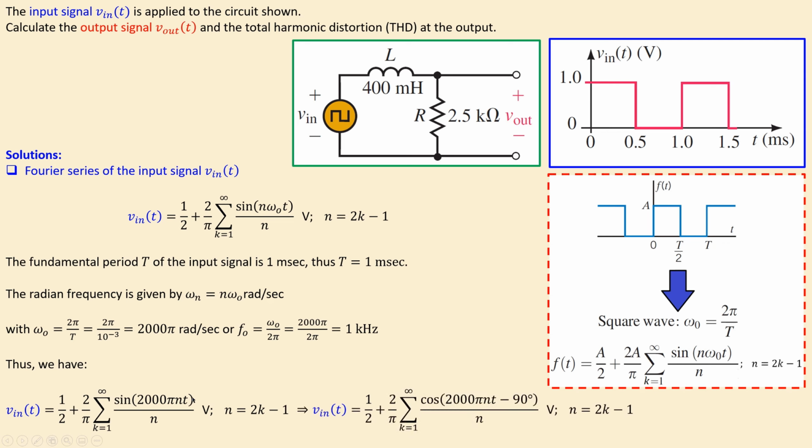If you of course want to use this expression in a cosine form, which is the reference we use as we move on to the complex plane, to the phasors, then we need to rewrite the sine as a cosine waveform. Then we have to subtract 90 degrees. So if you want to write down your sine waveforms as cosines, then this term must be shifted by minus 90 degrees. Then this expression will be exactly the same as this one.